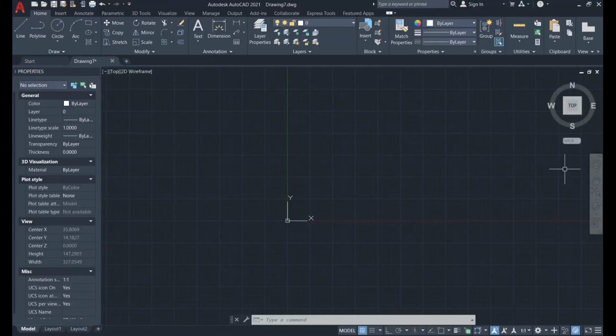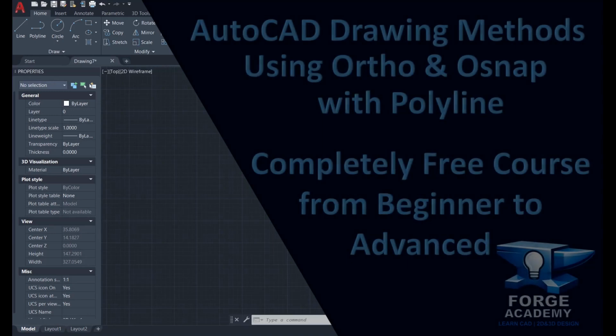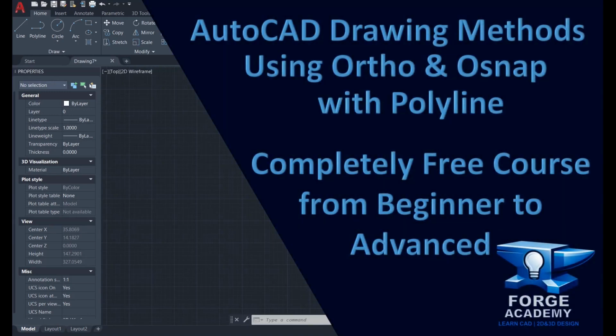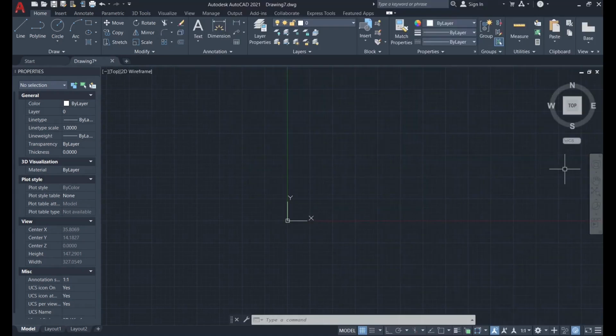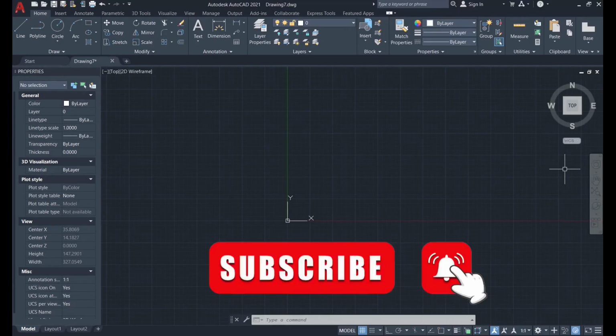As usual, I'm Nick, your host, and today we are going with the third video from our free AutoCAD course from beginners to advanced users. Today we are going to learn about the three methods to draw a line in AutoCAD: the Cartesian method that we have also learned in the previous video, the polar method, and also the distance method to draw a line. We will learn about the snap and the ortho and polyline command in this tutorial. That being said, let's move on with our third tutorial for AutoCAD.